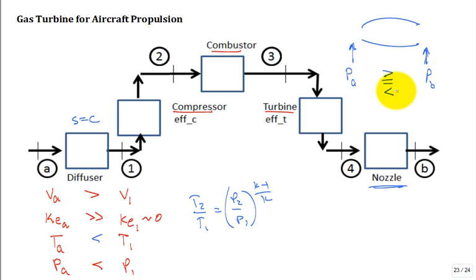They're equal. The streamlines are straight, there's no radius of curvature, and the pressure outside is the same as here. And then as I march through, it's a constant pressure, PA equal to PB. Very good. So we got that the pressure at B is equal to the pressure at A.